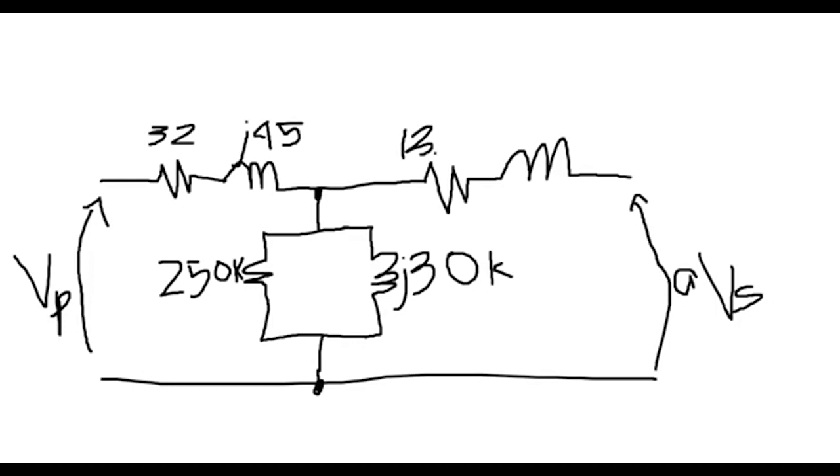For the values that we acquired a while ago, we have the secondary impedance as referred to the primary coil. Next is the reactance, j16.7. Let us indicate the current present. Since we are on the secondary side, it is I2 over the turns ratio.